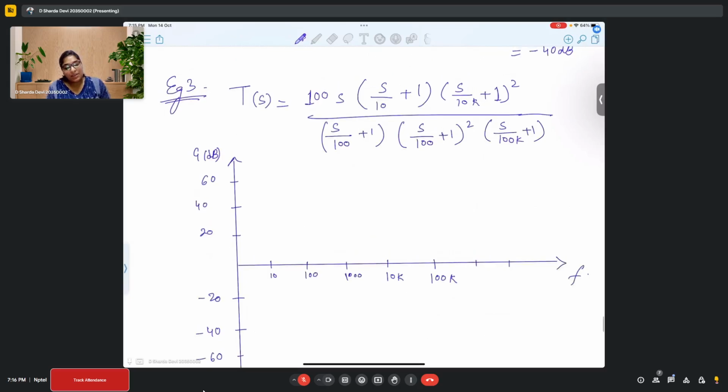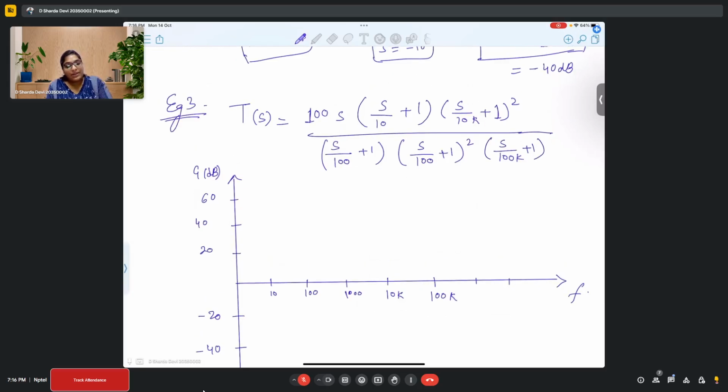Right? Now here, first of all, tell me where are my poles and zeros. So where are all my zeros? What is the location of my zeros? 0, then 10, and 10K. 10K. How many? Is it a single zero? Sorry, two zeros. 10K, 10K. Two zeros, right? So it's very important to also see how many zeros.